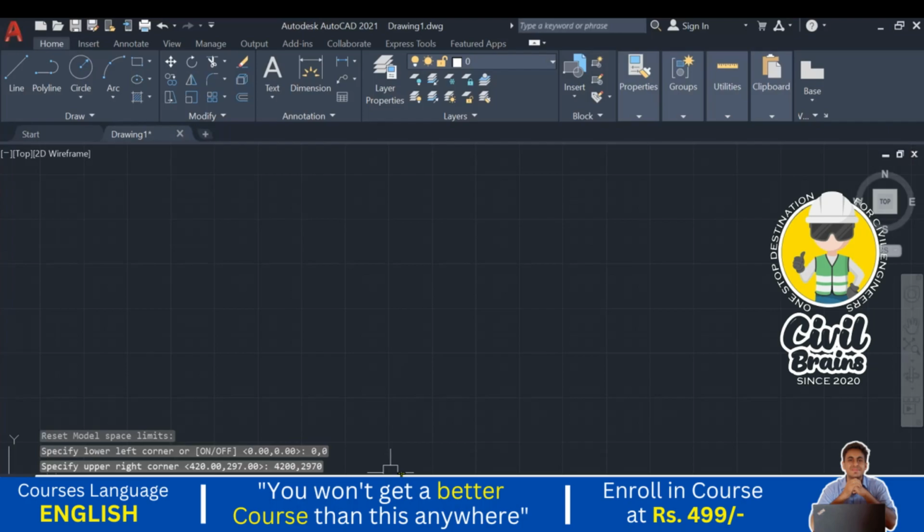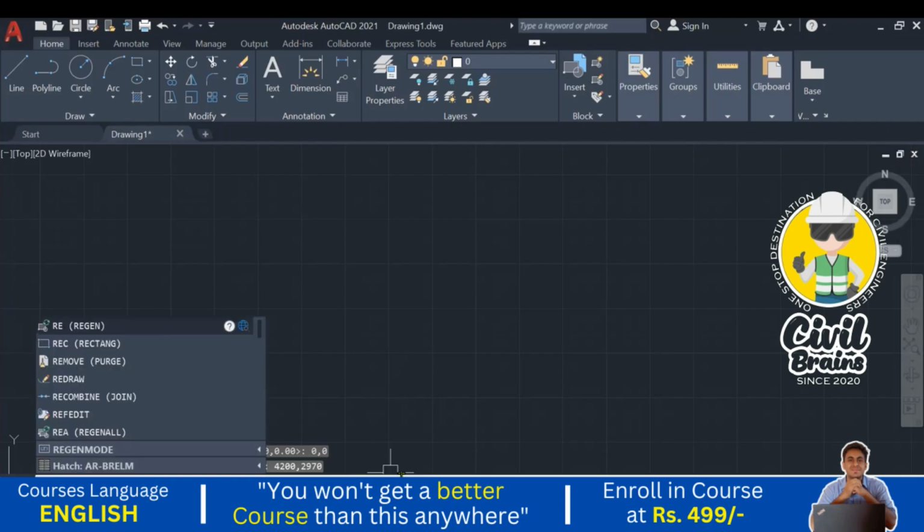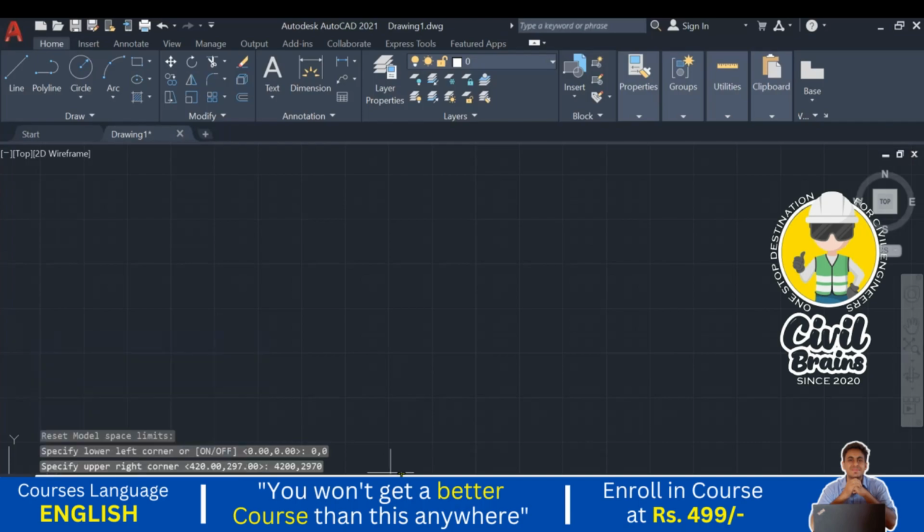Next, after setting the limits, we go to the rectangle command, press enter, and specify the corner 0,0, press enter.